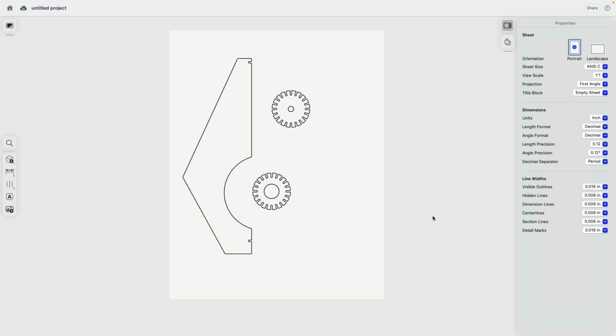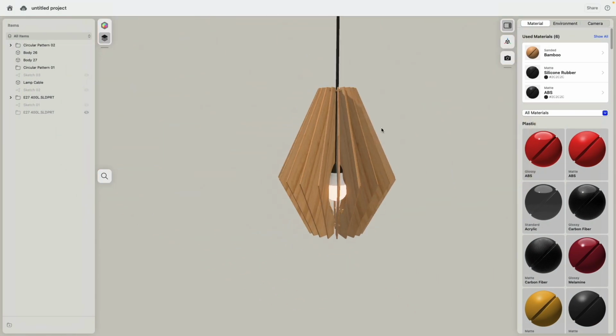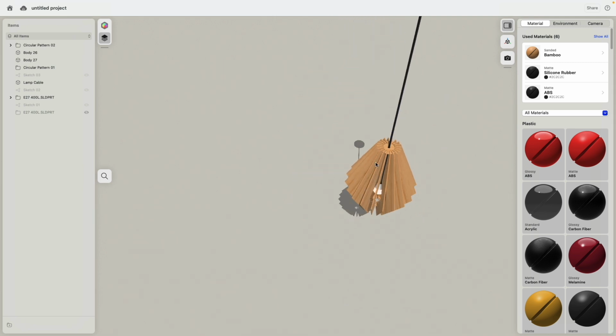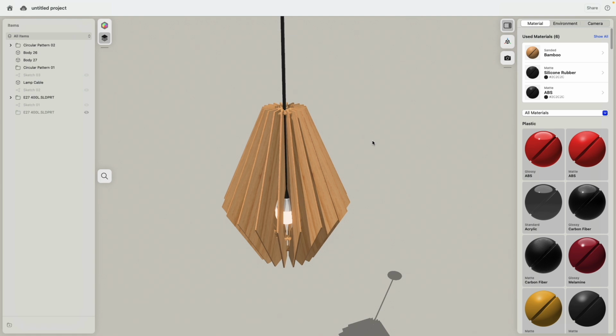The top and the bottom part we only cut one time, and then the other element, now we have to cut this one 20 times, and then we can actually put this together. And with this, we finished this exercise. That's actually how easy it is to prototype and then design. And in the end, if you would have access to a laser cutter, make a physical prototype. And that's it.